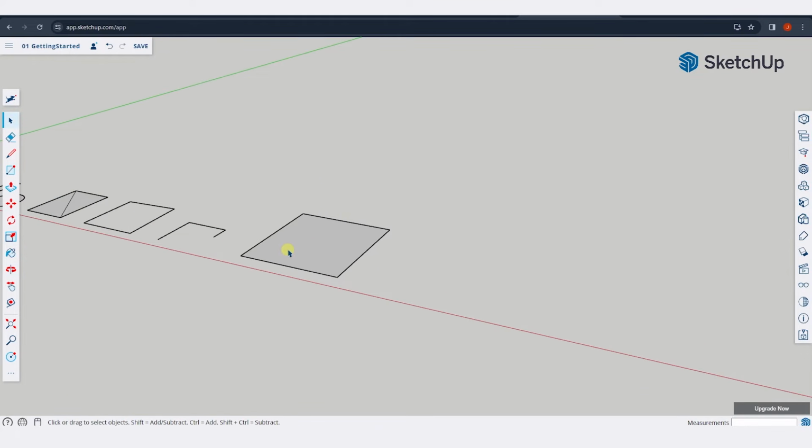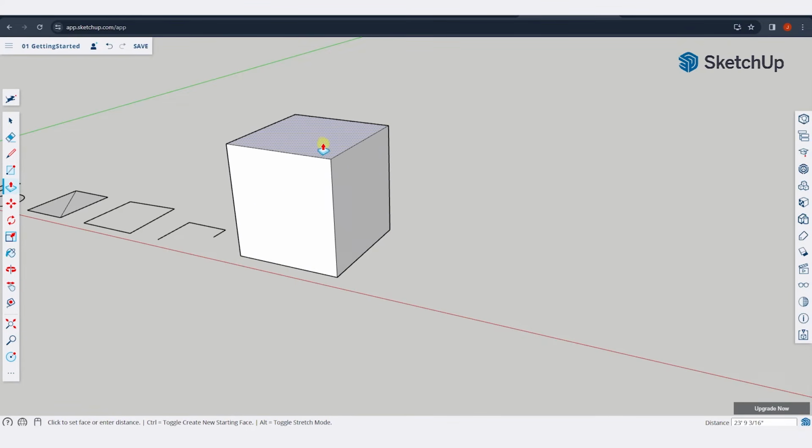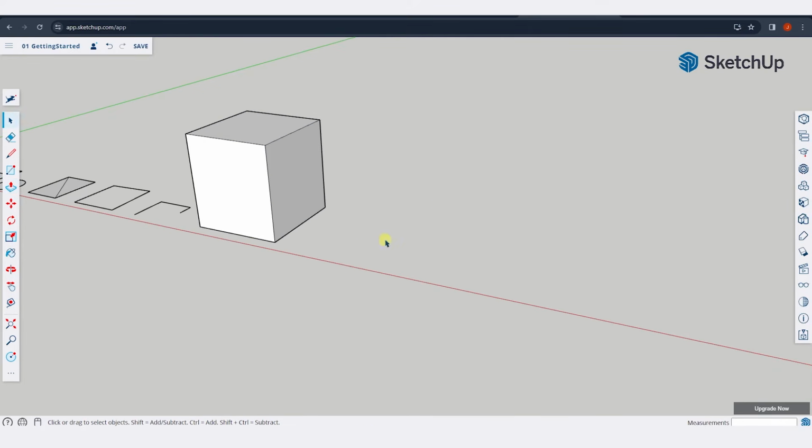Well, you can take this object and say you wanted to draw it in 3D. Now you could come in here and just draw in a couple lines really quick in order to get this to 3D, but that's really kind of time consuming, right? So I'm going to tap the E key and click and drag across this to erase it. What I can do instead is I can use a tool called the push-pull tool. What the push-pull tool is going to do, and you can either click on it or tap the P key on your keyboard, is allow you to mouse over a face like this and move your mouse in order to extrude a shape to 3D. So I can single click again in order to place this just like this.